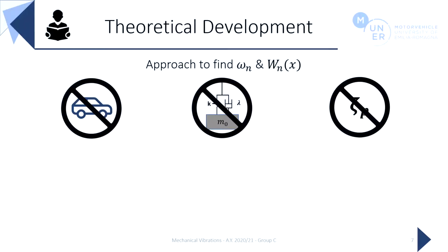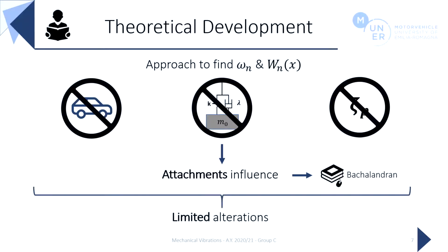As a matter of fact, from our research, numerous papers show how to work around the effect of attachments, such as the DVA on a bridge, on the results of the Eigen problem in beam vibration, and we included also a reference to one by Pellicano if you're interested. Nonetheless, since we are talking about a civil engineering case, where the extra mass represented by the DVA is very small and so is the effect of the structural damping, these alterations will be extremely limited and will determine our approximation to be fully reasonable.